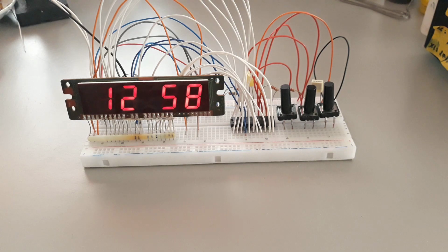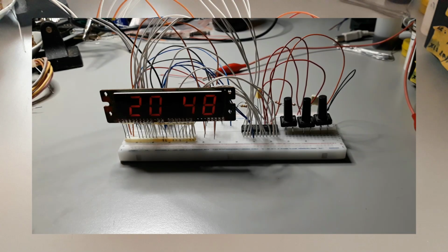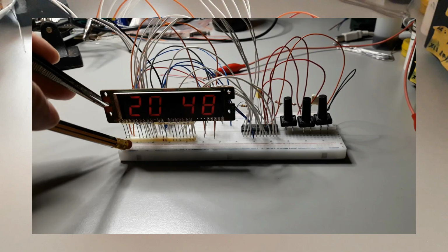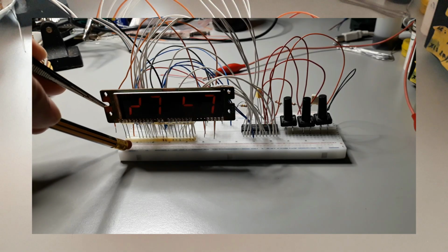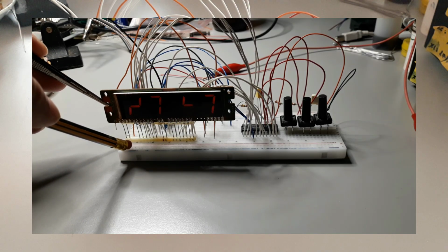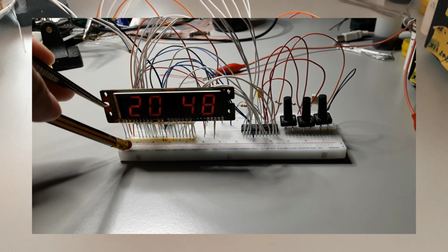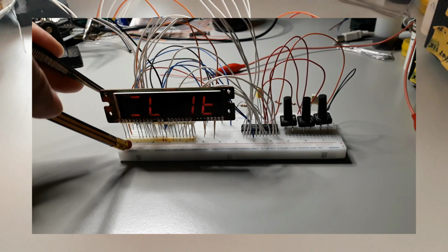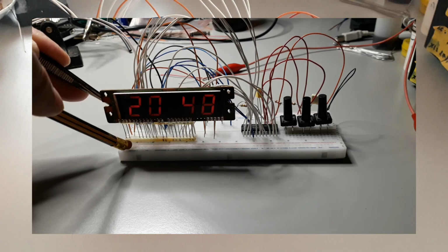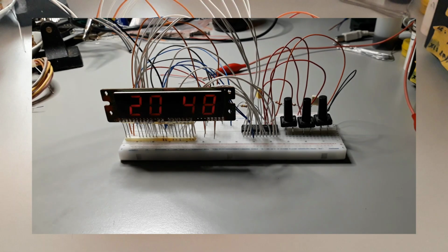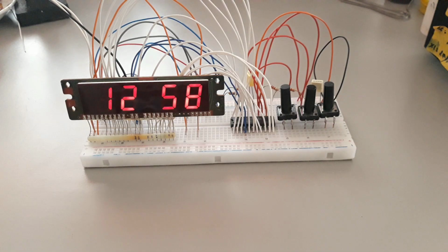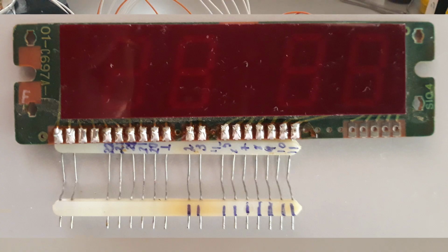To demonstrate how the segments are controlled through the two electrical phases, I will perform a simple test. First, I will disconnect phase 1. At that point, only the segments controlled by phase 2 will remain illuminated. Then, I will reconnect phase 1 and disconnect phase 2. This leaves only the segments associated with phase 1 illuminated. It is a simple demonstration, but it clearly shows how the display multiplexing method works.